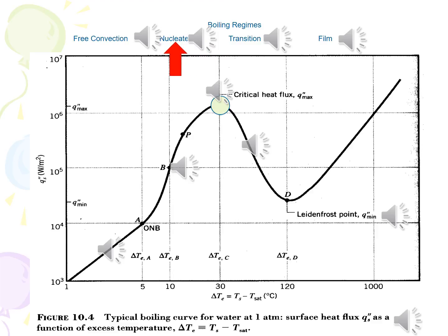This is as you often have imperfect sites on the hot surface that heat up more and act as nuclei for the production of vapor bubbles. Here convection heat transfer is increased due to advection, caused by rising bubbles of steam. As you approach the critical heat flux, however, more and more of the hot surface becomes covered in vapor. Heat transfer from a surface to a vapor is slower due to the low conductivity of the vapor. This then more and more cancels the positive advection effect of rising vapor, causing the maximum heat flux to be reached.